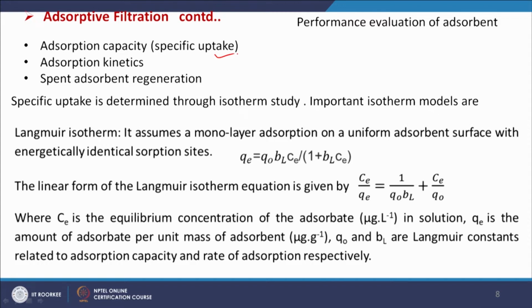And adsorption kinetics: what is the rate of the adsorption? So, what will be the retention time we have to provide during the removal of the pollutants from the wastewater? So, that adsorption kinetics is also important, and after that the spent adsorbent management or regeneration: what we will do with the spent adsorbent, that is also an issue.